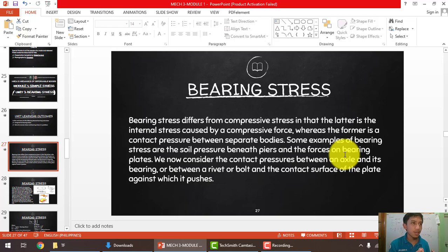How are we going to connect this steel to the concrete? We use what we call bearing plates. You put a steel plate on the shape of the rectangular concrete column, and that is where you attach your steel by means of bolts or welding.